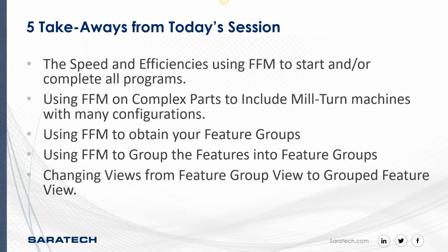And changing views from the feature group view to the group feature view in the feature navigator. That's important to me to let you understand, because it's very good to be able to see the feature groups so that when you go to the geometry view of the Operation Navigator, you understand what those top level feature groups are and not seeing the features themselves.